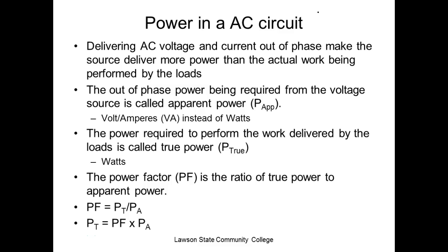But you got to understand the power grid has to support apparent power, which means all the transformers would have to support apparent power. All the conductors will have to support apparent power. And that would cost the power company so much money that it behooves them to run a 100% power factor. Now, they have different ways that they correct for power factor. Remember, capacitors and inductors are just opposite of each other.